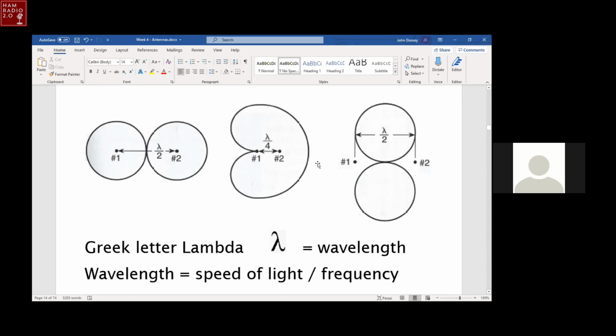I read that and thought, well, that's confusing because the pattern looked the same, but in the book it just shows the antennas, one up here where lambda over 2 is, and the other one down here in the middle of the other circle of the pattern. So here I wanted to look at how you can have the antennas at the same physical position and just change the phasing of the feed, and you switch from linear off the ends of the array to broadside to the array.